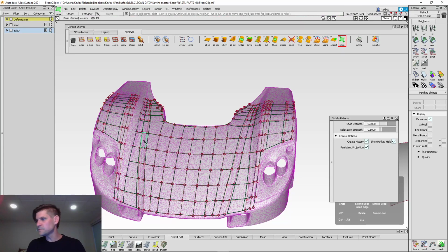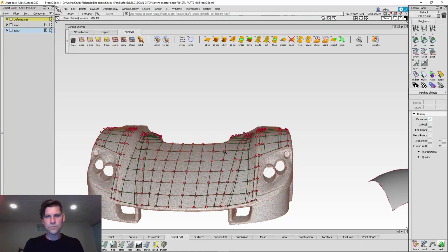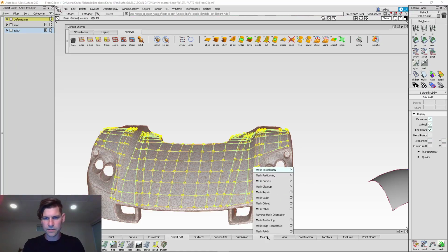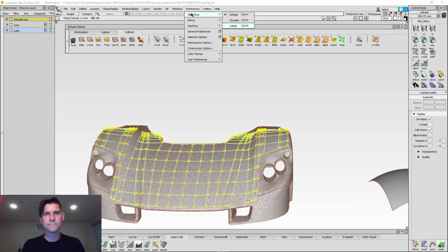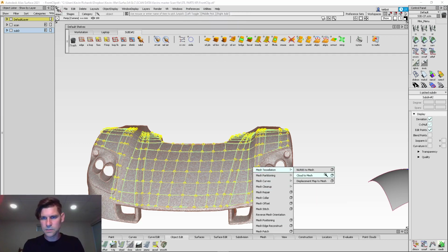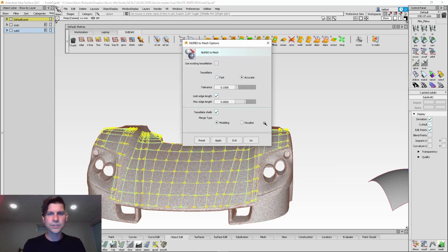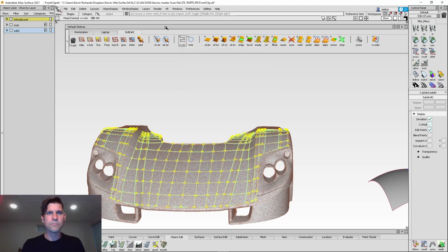Yeah, right. Subdiv to mesh is good for 3D printing. That's absolutely right. The one that I played with, I thought I just showed it the other day. It basically allowed all of the mesh or the NURBS limit surfaces to be automatically stitched together. If you do a NURBS to mesh, then each of these patches are separate. But where in the world is it? Default. And I thought it was here. Yeah, because we don't want tessellation, because this will make a tessellation for each boundary.